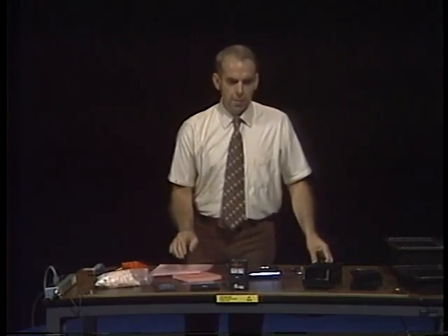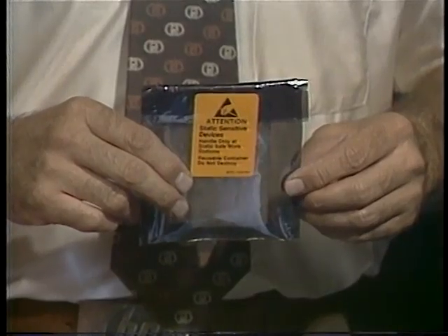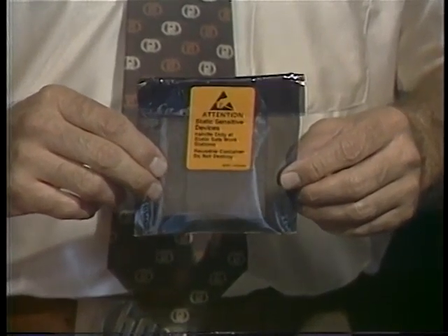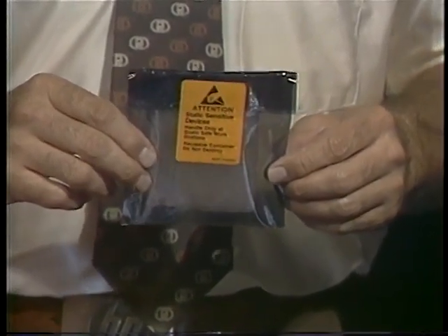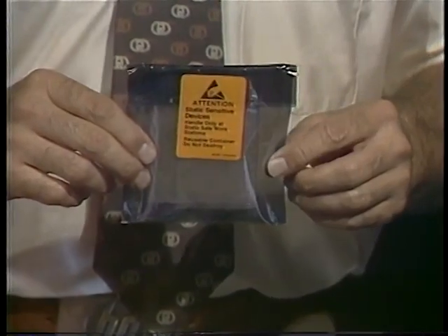The final step in anti-static packaging is best illustrated by this metallized bag, and that is to label it. Make sure that the recipient of this package knows that he must only open it and handle the contents at a static safe workstation.